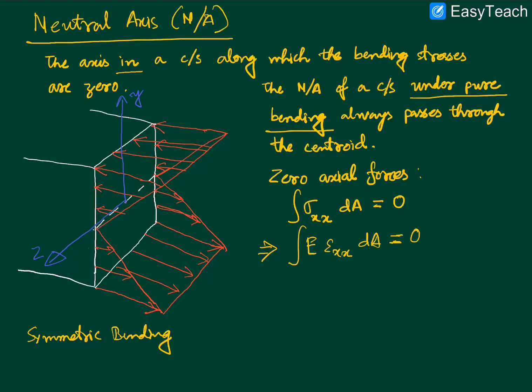limitations of the Euler-Bernoulli beam hypothesis. And within that Euler-Bernoulli beam hypothesis, we do not allow for any strains along the y direction or the z direction. We are only considering strains which are normal to the cross section. So we are only considering the possibility of length changes along the longitudinal axis of the beam.